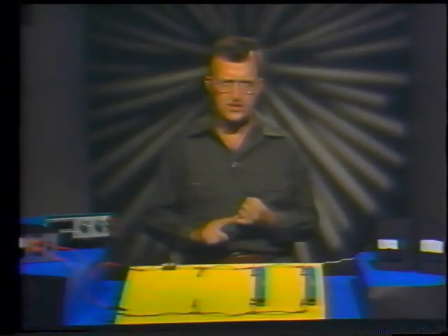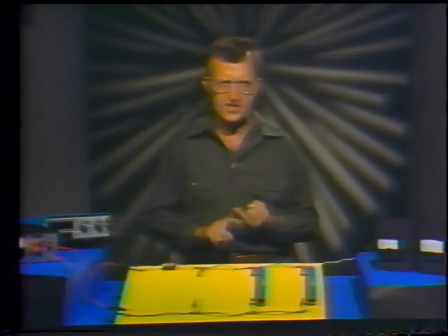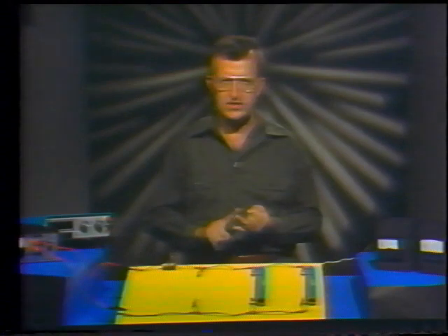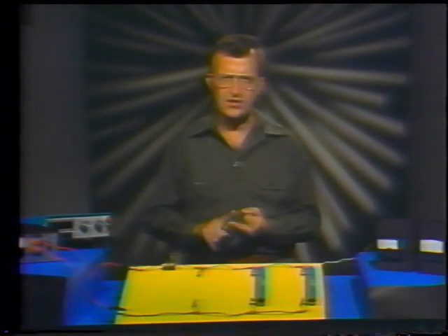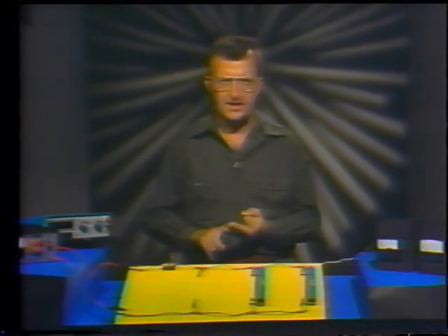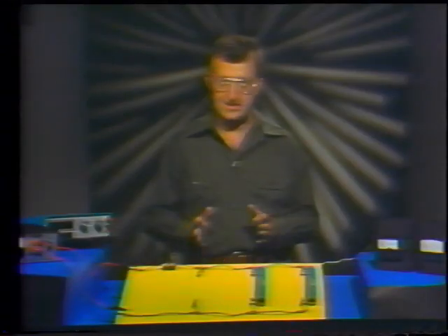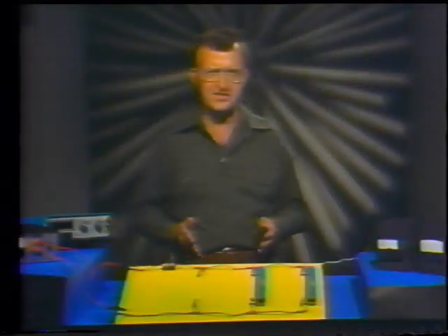First, the voltage across each branch of a parallel circuit equals the source voltage. Second, the total current in the circuit is equal to the sum of the currents in each branch. And third, the total circuit resistance is less than the resistance in any of the branches. And it takes a lot more time to learn these facts than it does to say them.